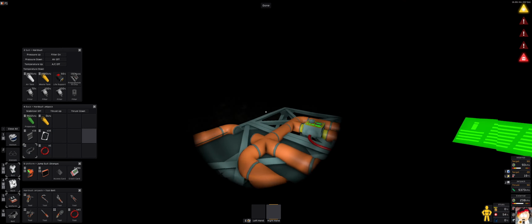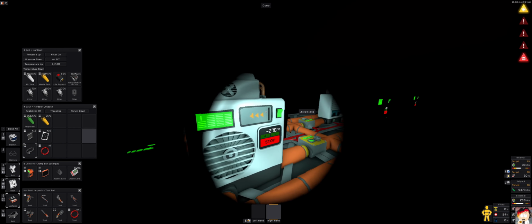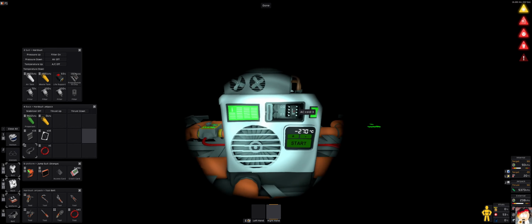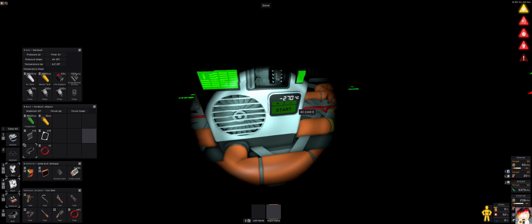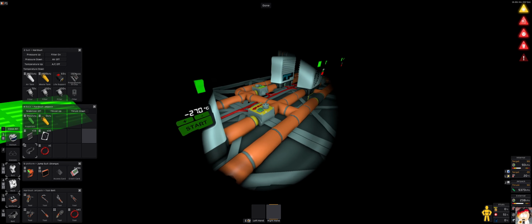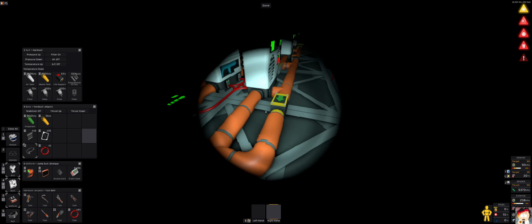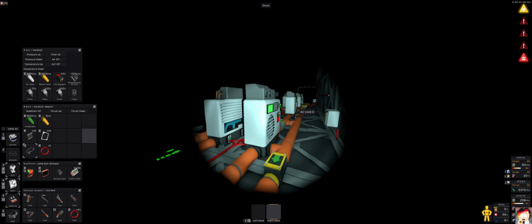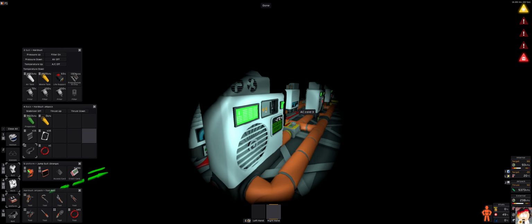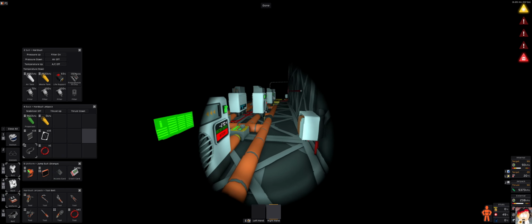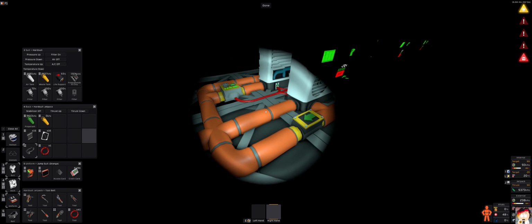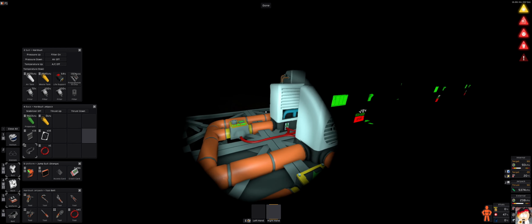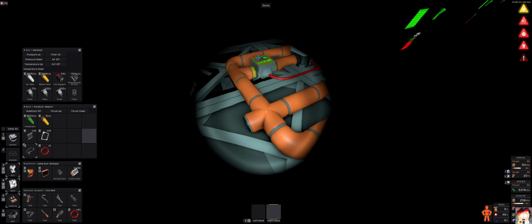Now, I'm gonna leverage a little bit of functionality in the AC code from Elmo. When you open it, it's gonna pause directly the AC and its related pump. So effectively, the tiny code I'm gonna put later on over here will be: if the temperature is below this, pretty much set all of them to open, and they're gonna trigger their pause or shutdown code, right? Then if the temperature rises above, let's say, -60, turn them on and keep cooling. This way, this will be pretty much stopping and starting on demand, A, saving power, and B, avoiding this condensate.